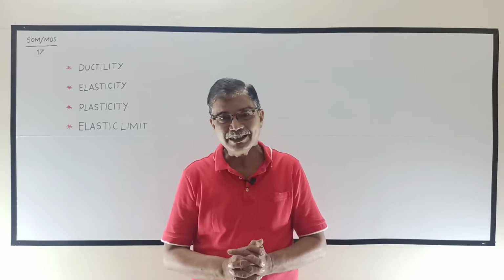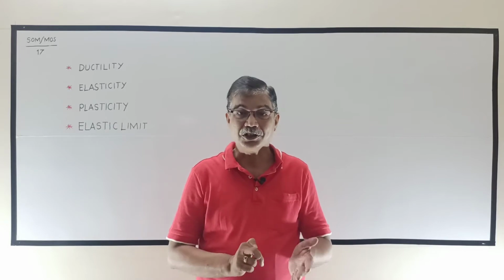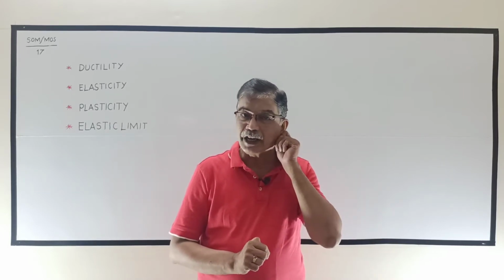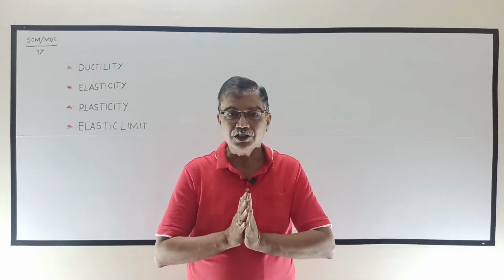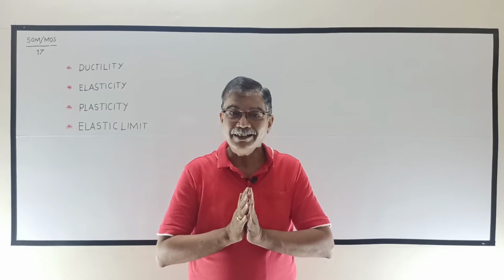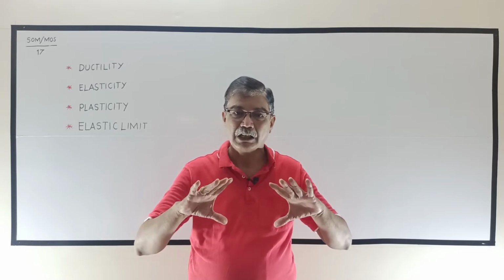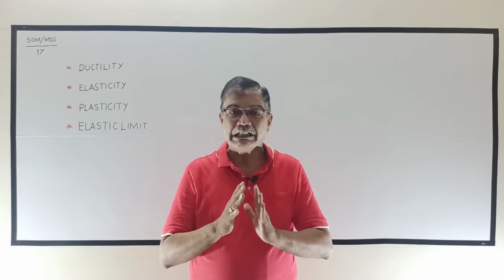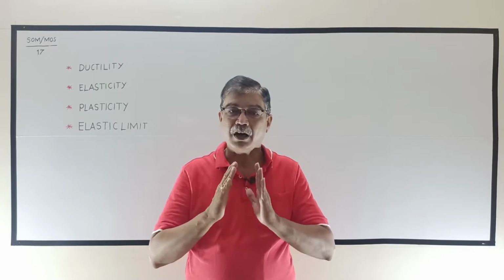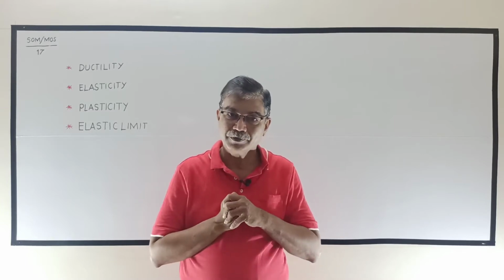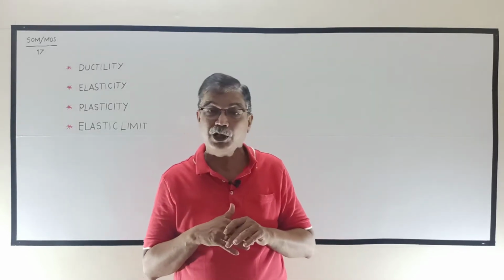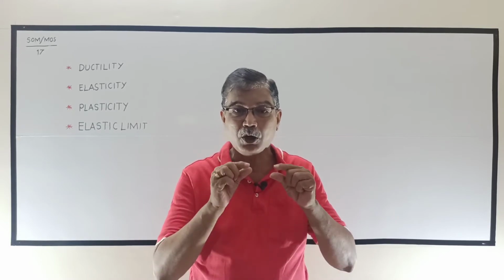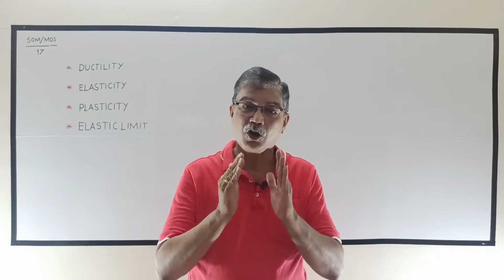As far as steel structures are concerned, mild steel structural elements are used, because as they are ductile in nature, even if that particular structure is overloaded, it gives some deformations, due to which we get the prior intimation of the impending failure. Now once again I will repeat, ductility is the property of the material by virtue of which it can be drawn into smaller cross sections without causing failure.